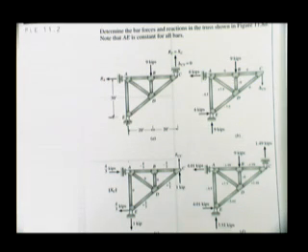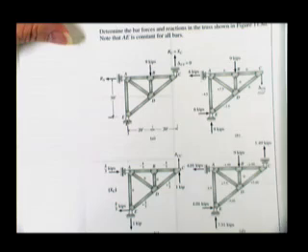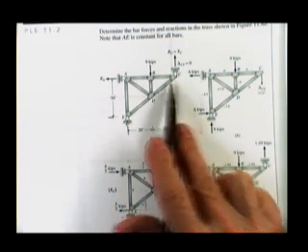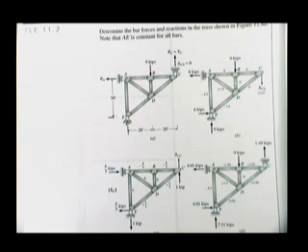Sadly, the structure deflects in the C vertical direction, or at least there's a possibility that it does. And therefore, the structure does not deform compatibly with the way it's supposed to deform. Therefore, we'll come back in and put some forces on it to make that deflection that we don't want go away. We never cared about the horizontal deflection at C, and therefore we don't care about it now.